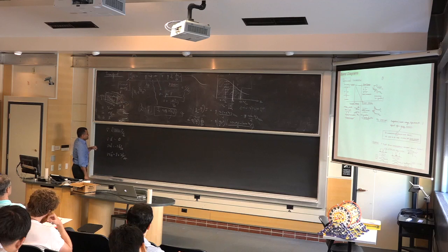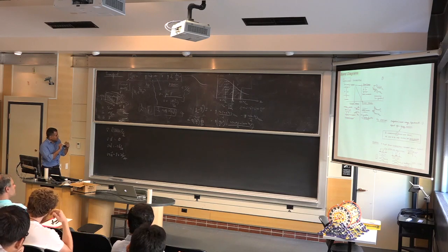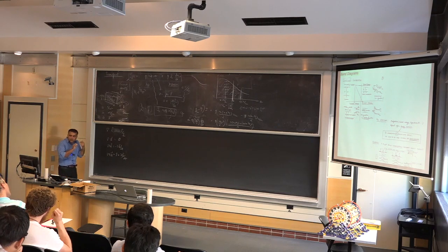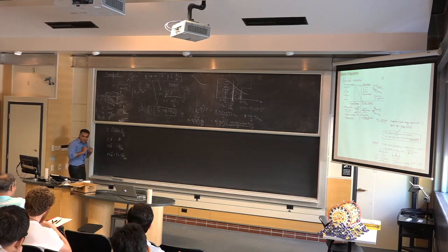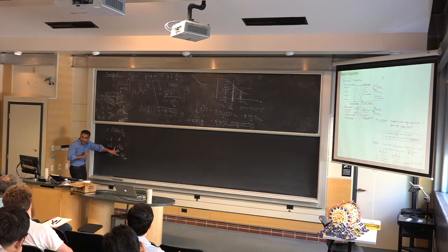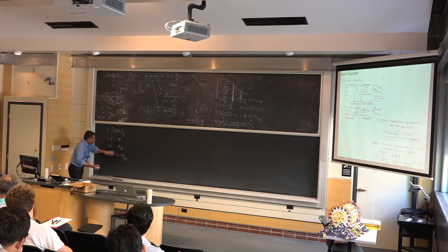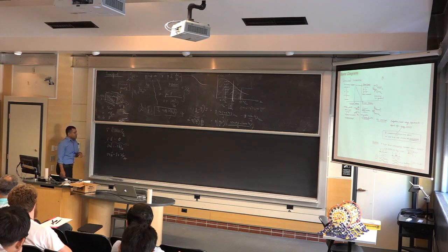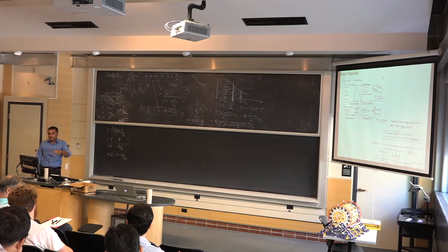But if we are looking at transistors in the time domain, meaning I'm doing a 300 gigahertz circuit or something like that, then I will be worried about these 2 terms. I use this to design the device and design the structures and all that stuff. But right now, in band diagrams, we're going to look at only electrostatics. So all d by dt is 0 for us.